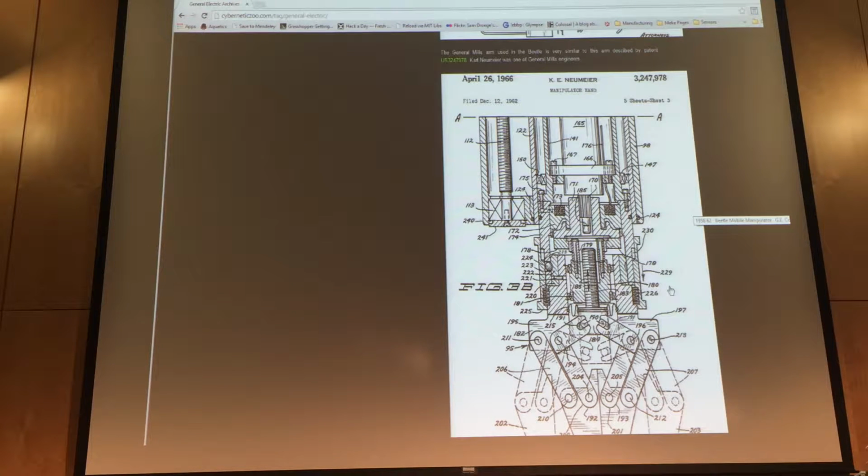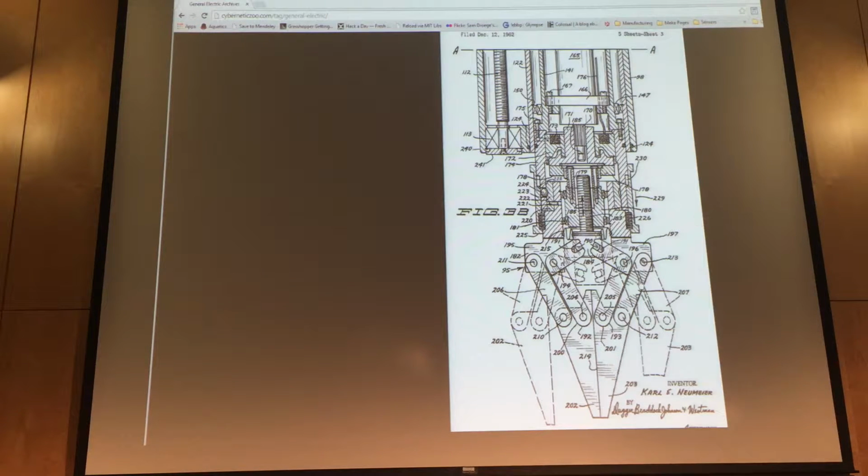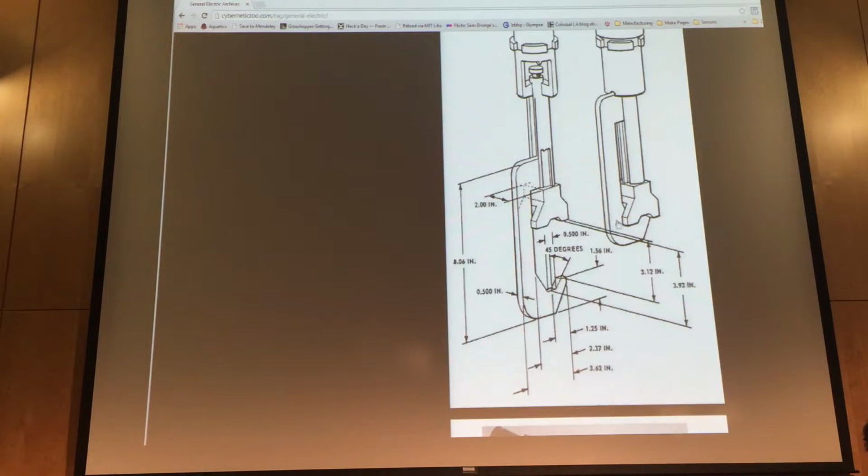You may have to look at it for a little while. The resolution on here, my screen is a little bit better, so you can see a little bit better. But what they're showing here is a gripper mechanism. There's a screw that drives back and forth here. It's driven by this nut that is sitting on some sort of bearings. It's rotated by this guy, which is sitting on these bearings, which is driven by this motor. So it's a little hard to see, it's a little messy, but when you start digging into it, you can start seeing where the bearing forces are, where the bearing constraints are. And so anyway, it's just fun to start to dig through these things.